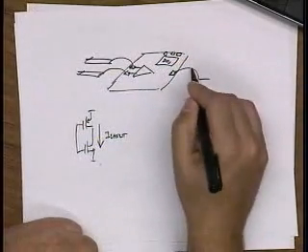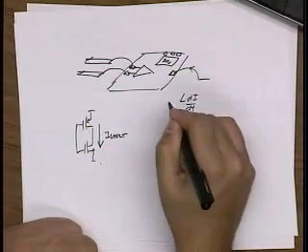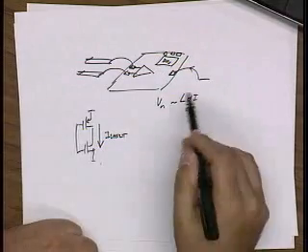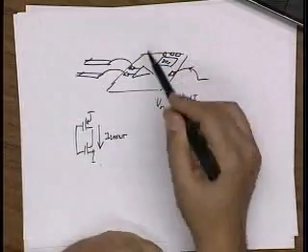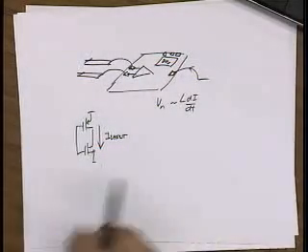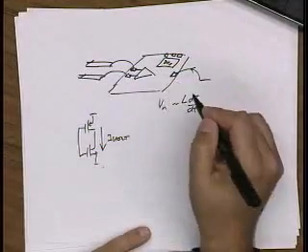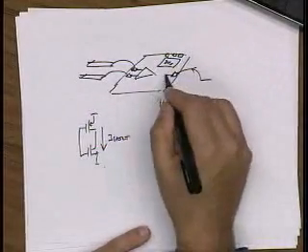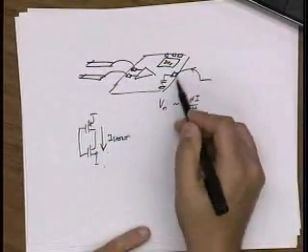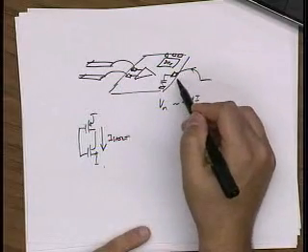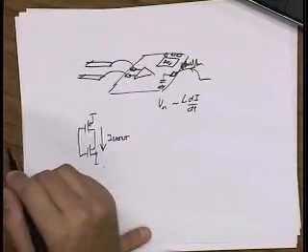Because of the inductance of the power supply, I get L dI/dt kind of noise. I call it noise, of course it's not really noise, but we call it noise because there are so many inverters here all switching at different times that it's kind of pseudo-random, right? And so it looks like a random perturbation. So how do I fight this? Well, I put a really big bypass capacitor on chip. But I can only make this so big. So at the end of the day, I'm going to have noise on this supply.